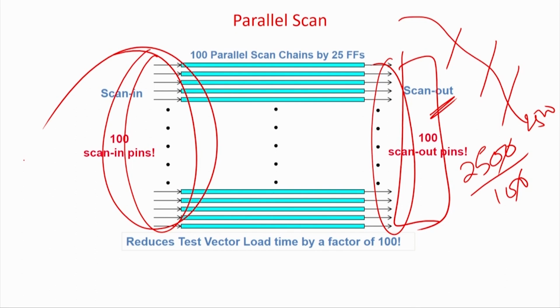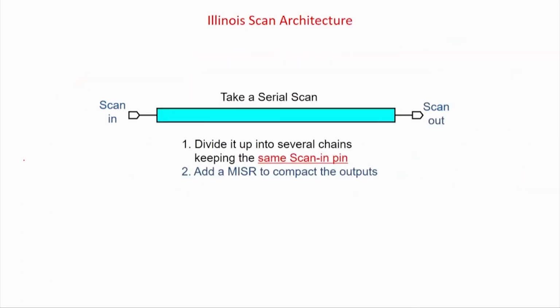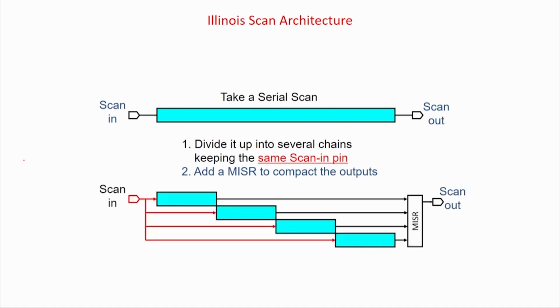Of course there is; we do not talk about external pin outs as 100 because they do some sort of compaction. Interesting. Say this is a big scan chain, and I partition it into 1, 2, 3 and 4. So I require 1, 2, 3, 4 pin outs to do it. But can I reorient or organize the circuit in such a fashion that I will have a single pin to load all the circuits?